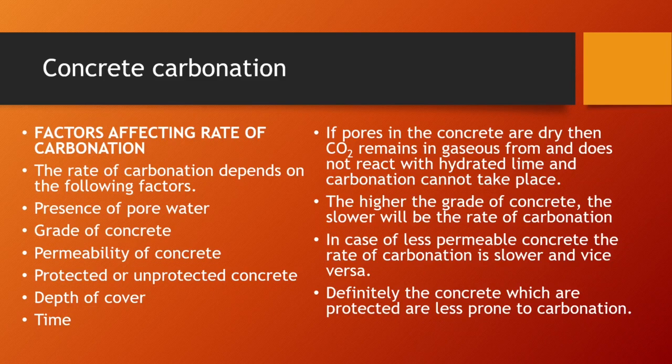The depth of cover. Effectively, typically you would have 50 mil cover between the formwork and the steel frame. So you put the reinforcement bar together in, say, a cage inside your formwork. The formwork is the mould. Then you put the steel inside.